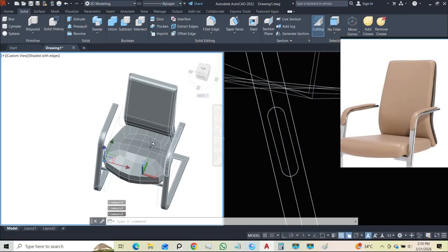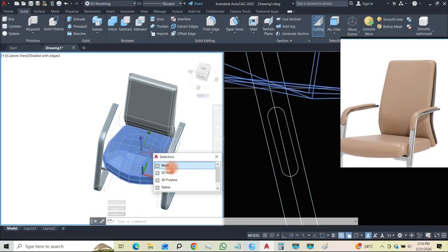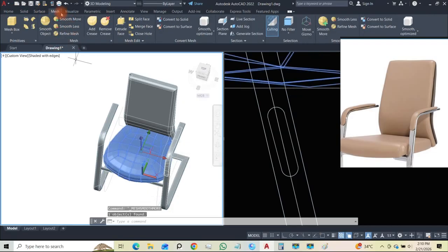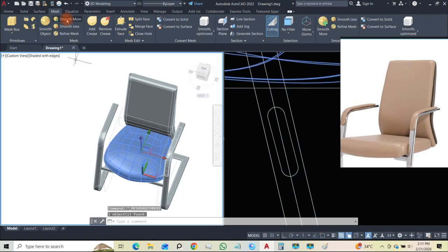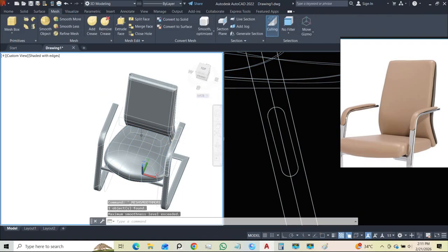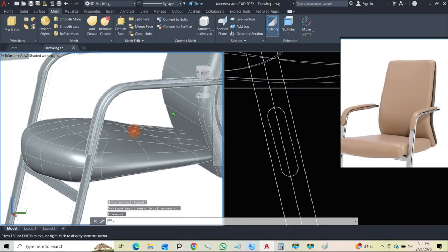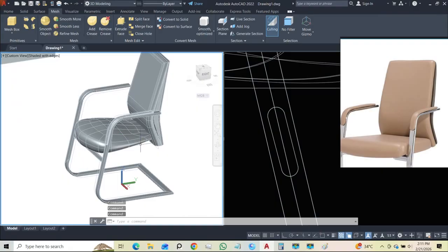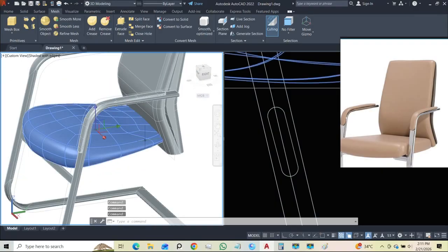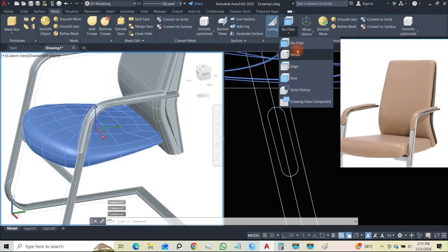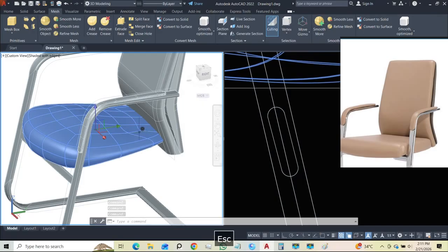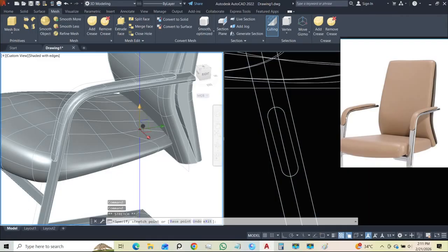So go to no filter, select it, select the mesh, and then come to your mesh, smoothing. It's going to smoothen it to the point where it will say you can't smoothen this anymore. See that? So we just have that to be done. So if I come here and I still go back to my point, nothing will happen because it still recognizes only these points. Okay, so I can start to use this to